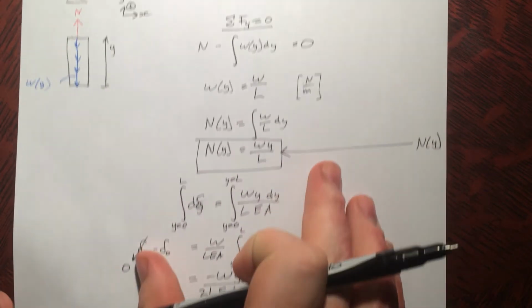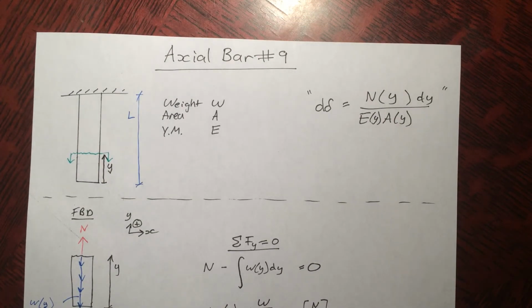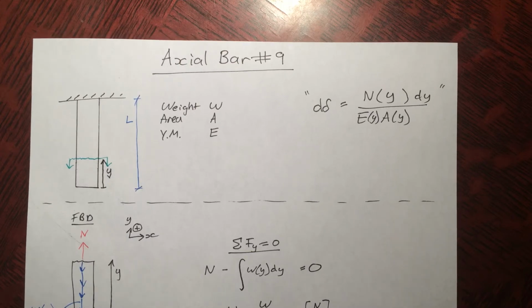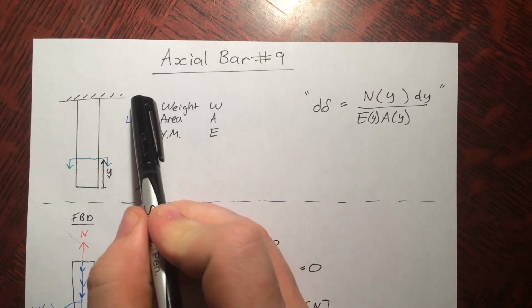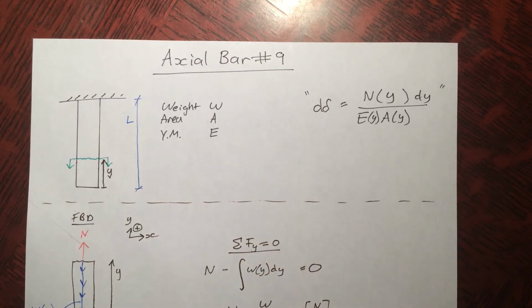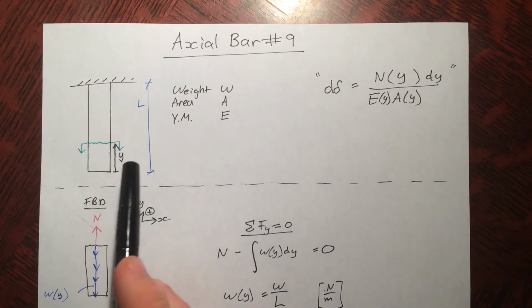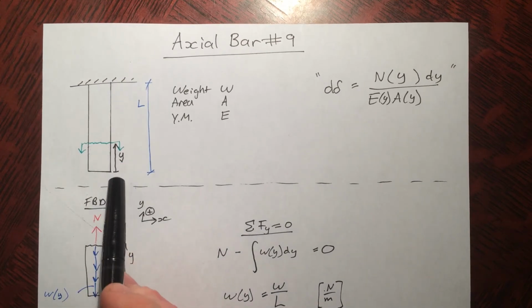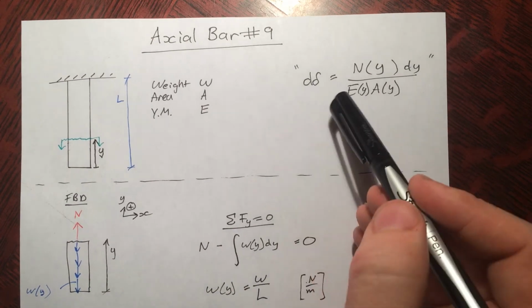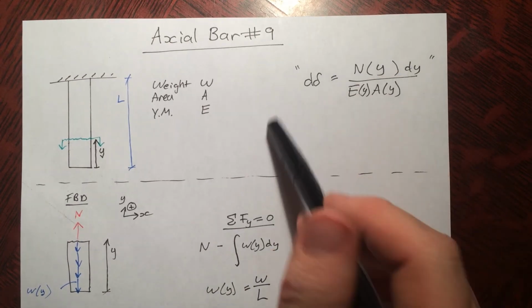Just to recap, I want to emphasize process once again, because if you have the right process down, you'll get the answer right 90% of the time or more. First, a nice clean initial picture. We show where we cut, and we define a coordinate system as y in this direction, which is reflected in the way we set up our equation.